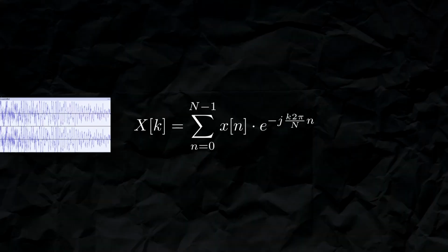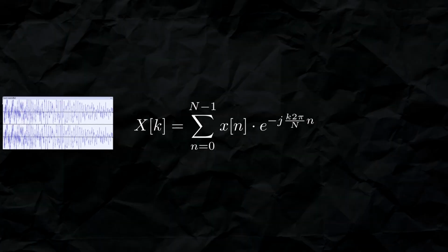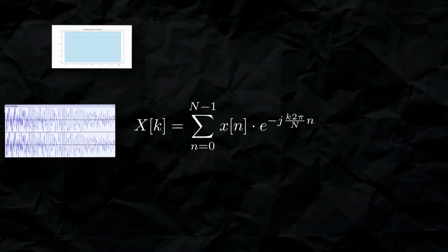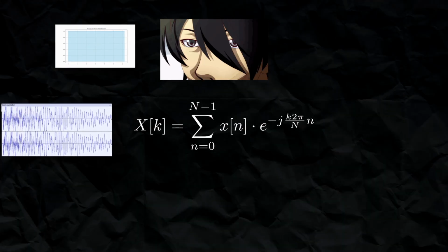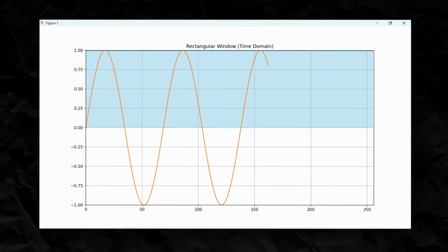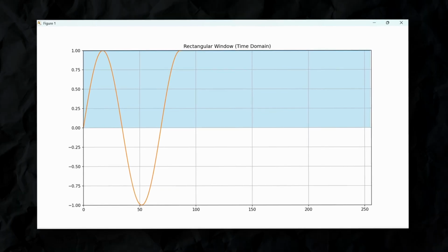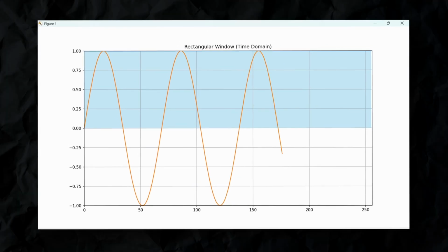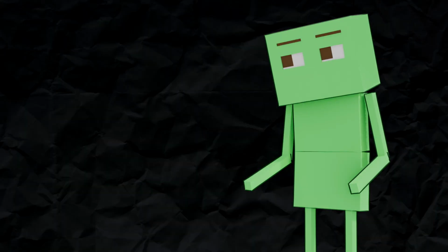Every time we input a piece of audio into our DFT, we're always giving it a rectangular window. Even if we're not manually doing it, the nature of the DFT just sees the audio as a rectangular windowed piece of signal. A rectangular window looks like this. It doesn't affect the amplitude of any points of our audio at all, and so whenever we have a non-periodic frequency in our full window and we don't have a frequency index or bin to mark it as, we get leakage.